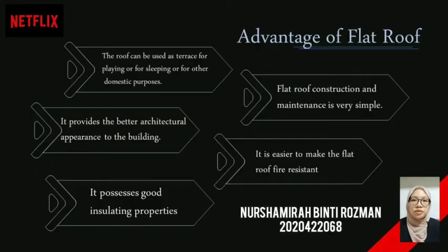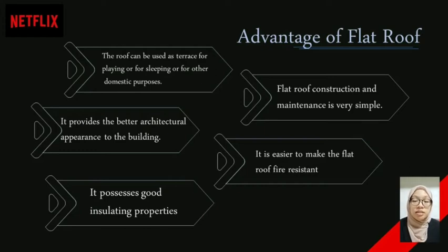The first, the roof can be used as a terrace for playing or sleeping or even other domestic purposes. Second, flat roof construction and maintenance is very simple. The third one is it provides a better architectural experience to the building. Fourth, it is easier to make the flat roof fire resistant. And lastly, it also possesses good insulating properties.